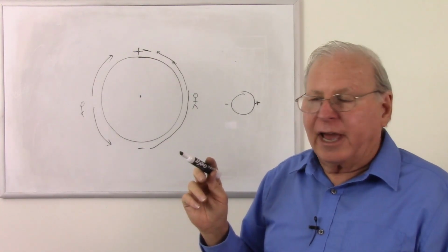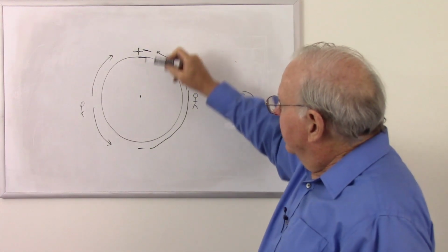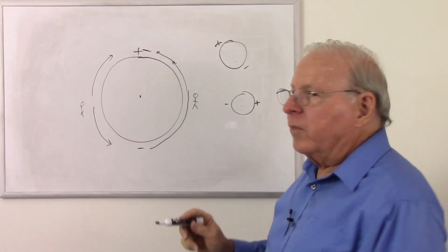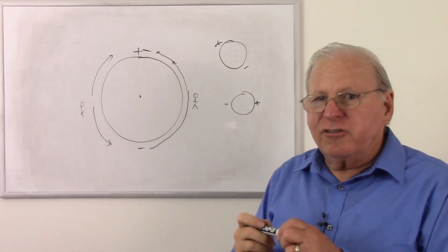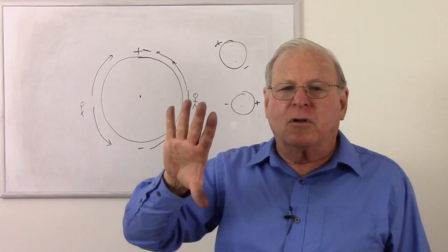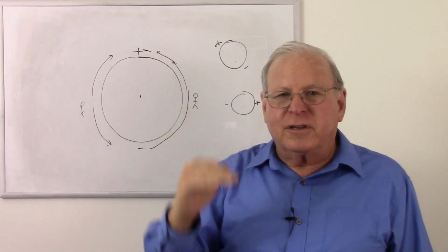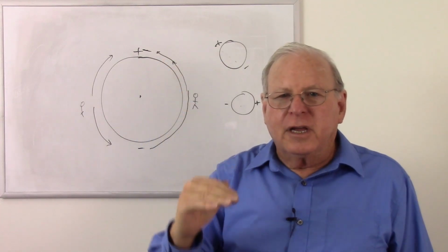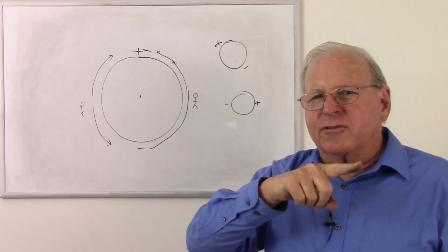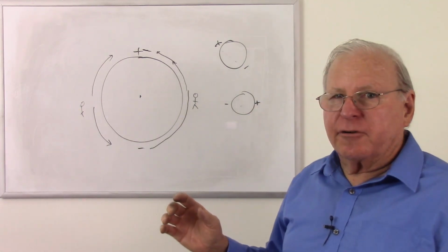That's something that sound doesn't have. Polarization depends on the orientation of that electric field. Is it vertical or horizontal or somewhere in between? So the polarization is the orientation of the electric field, and we'll call it usually either vertical or horizontal. If the electric field is oriented vertically, positive to negative, then it's a vertically polarized wave. But if we turn it sideways, where positive is left and negative is right, or vice versa, then it's a horizontally polarized wave. So that's a new thing. We have polarization with electromagnetic waves.